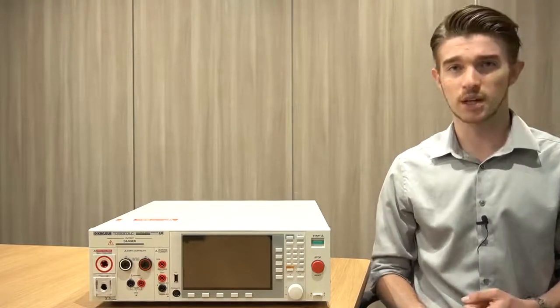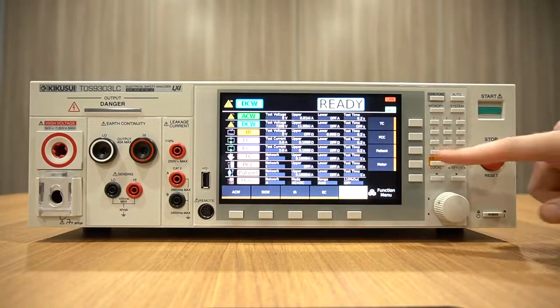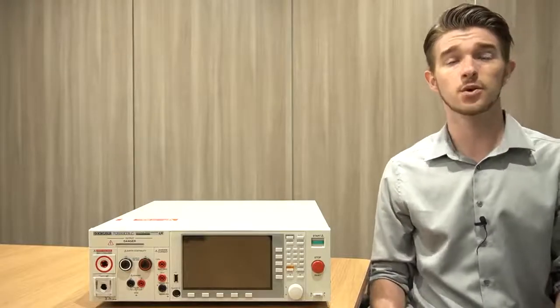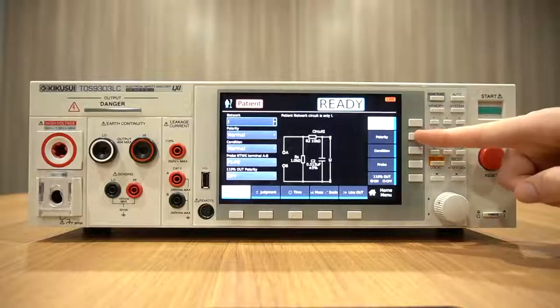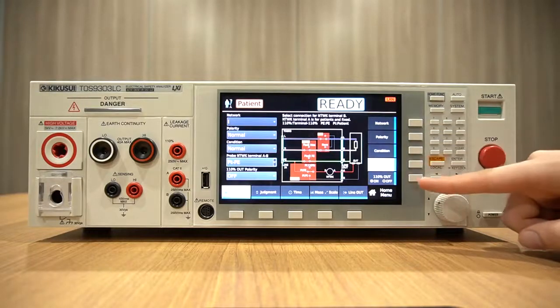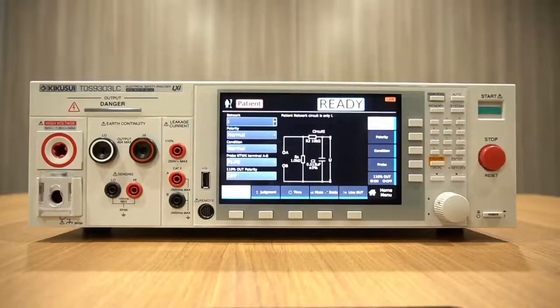In order to make your test settings, press LC from the function menu screen, and then press Patient. From here, you can configure a wide variety of settings, including polarity, upper and lower limits, test time, and measurement ranges. As you can see, the network is already configured as I, which represents IEC